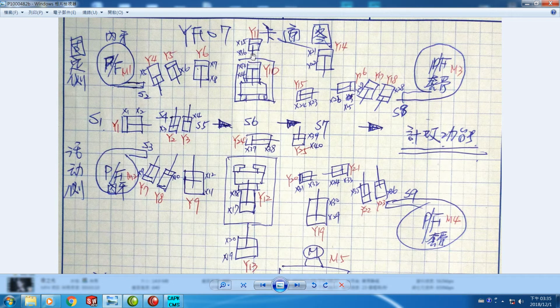As it goes to the end, S16 touched, the movement will stop in position, and then Y10 will turn on. Three teeth, 120 degrees in distance, will move toward the center to bite three holes at both sides of the aluminium bar.